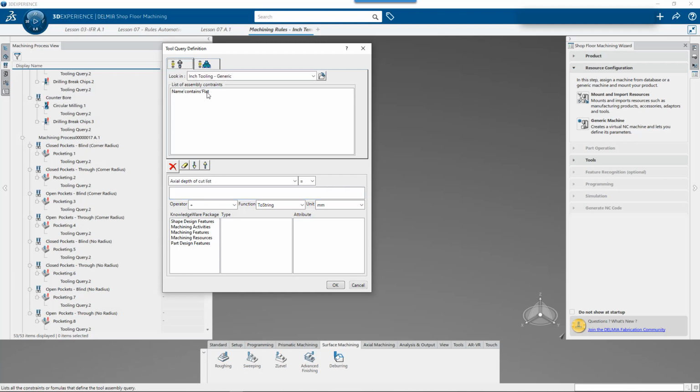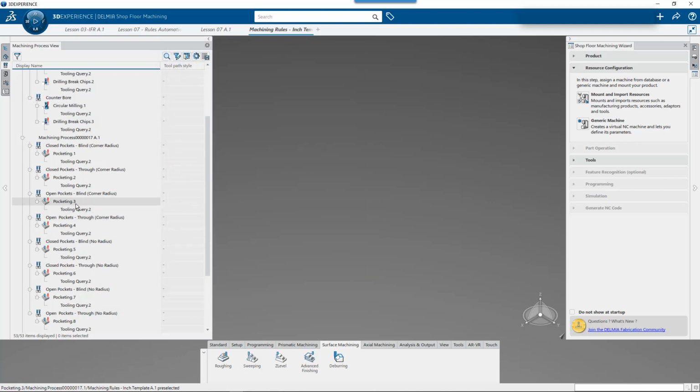And then it's also calling out that for this instance, it has to be a flat because I'm looking for one with no radius. So if it sees one with a radius, then I'm actually picking a hognose tool. So not only am I querying whether or not this operation is useful, I'm actually interrogating what that feature is to determine which tool I want to use, or whether I want to use a tool.